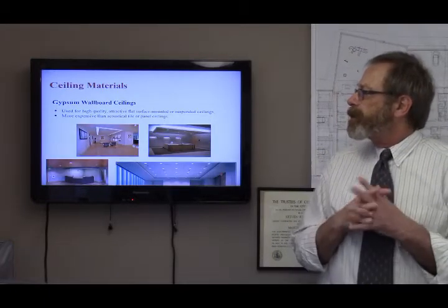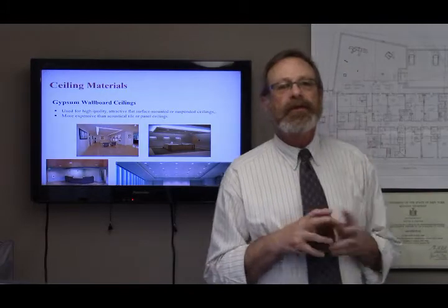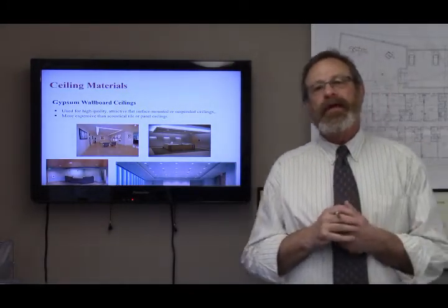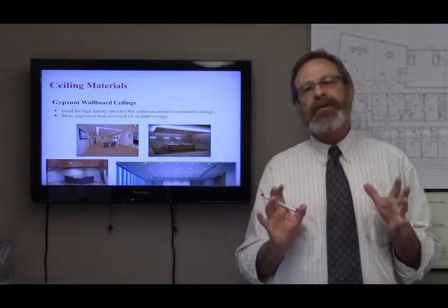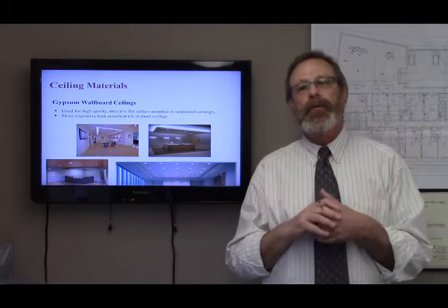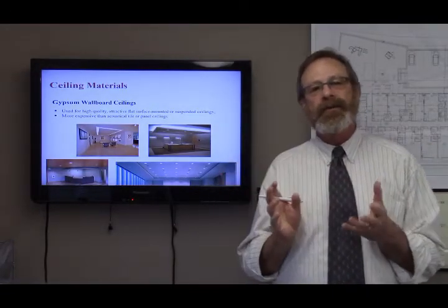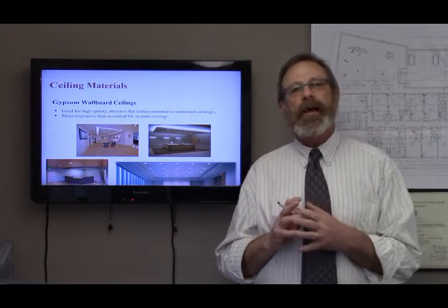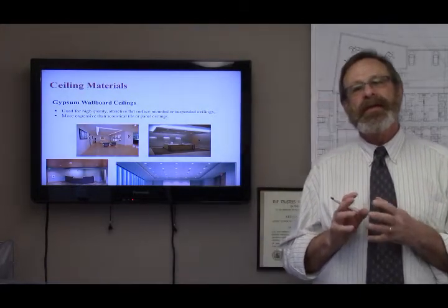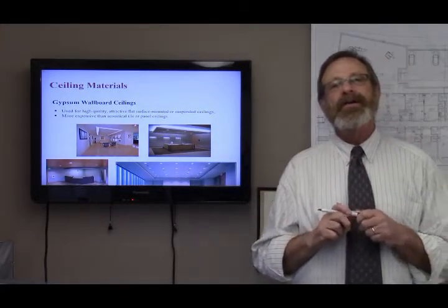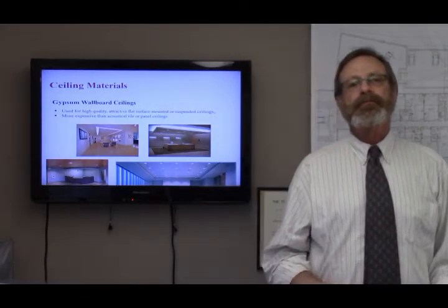Let's talk a little more in depth now about gypsum wallboard ceilings. Except in residential settings where gypsum wallboard can be attached directly to the underside of the wood framing of the floor above, gypsum wallboard ceilings in commercial applications are more labor intensive because they require a secondary support system.